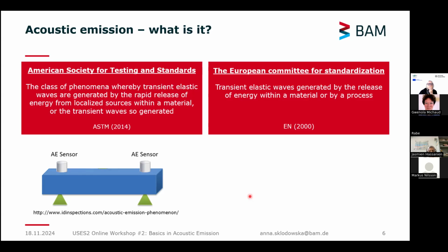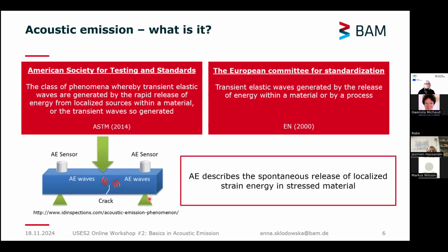Okay, so this one is long and maybe not the clearest one. The European Committee for Standardization, on the other hand, says that this is a transient elastic wave generated by the release of energy within the material or by a process. What it means is that we have, for example, a beam, we have sensors, we apply some kind of force on it, and a crack appears, which emits acoustic emission waves. So this is a very simplified definition. In simple words, we can say that acoustic emission describes the spontaneous release of localized strain energy in a stressed material.